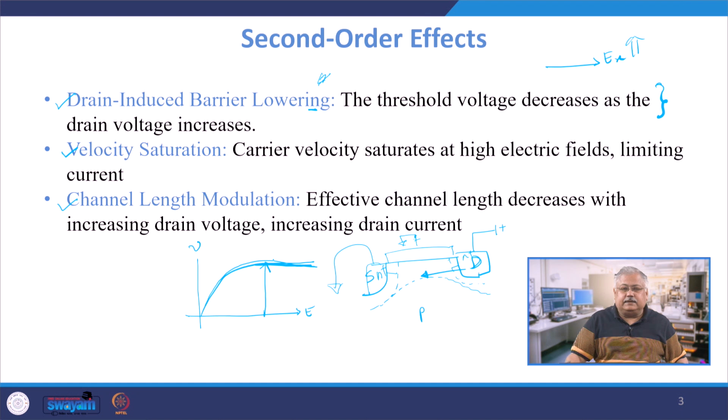And why is it like this? Because as you first increase the value of the electric field, velocity is given as mobility multiplied by electric field. So, assuming my mobility is constant, my velocity increases linearly with respect to electric field, and that is what is happening here. As you move slightly further, the electric field becomes larger, mobility is a non-linear function of electric field, and therefore velocity becomes a non-linear function of electric field in this region. After this, the velocity is constant, which means acceleration is 0.